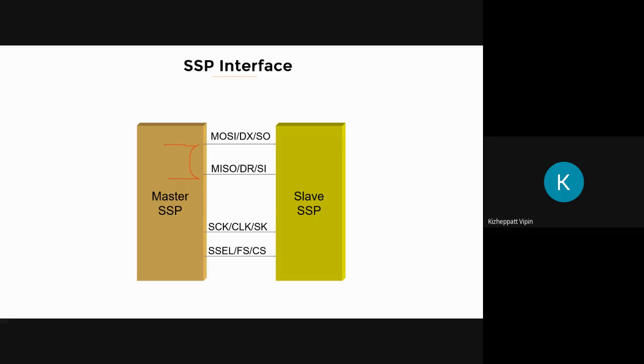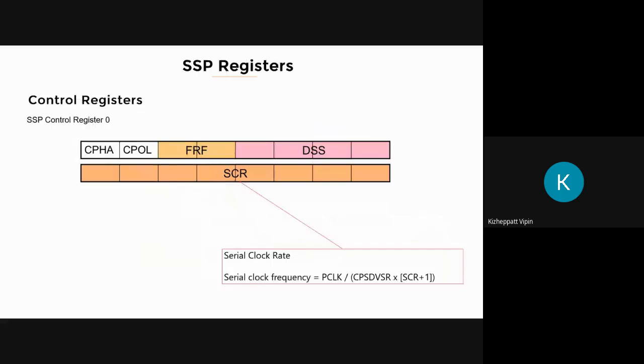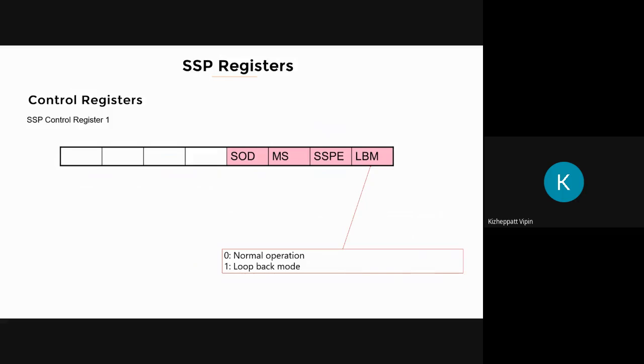Loopback is very useful while you are testing. You are sending some data. You want to check whether the data you are sending is actually going out. So if you enable loopback, you send some data, you will get the same data back. Then you can compare them and check whether it is working or not. Does that make sense? Okay, so that is where we can use loopback. Usually used during testing or to detect some error condition. Normal operation, that's why it's written like normal operation, so we will keep this bit 0.